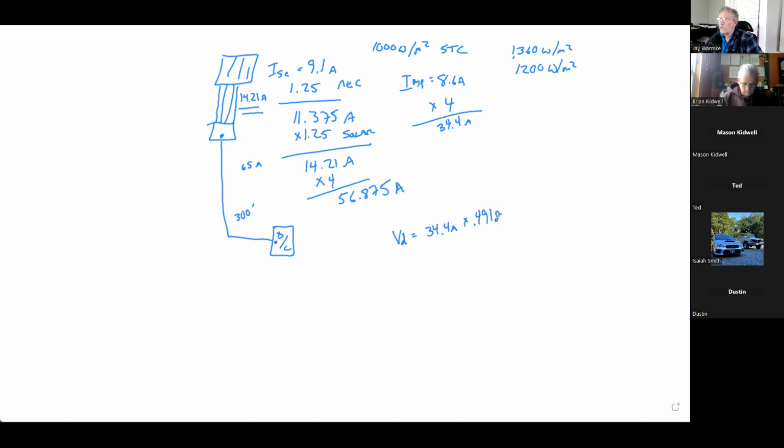0.491 ohms times, well, I said it's 300 feet. 300 feet times 2 divided by 1,000 is going to give me 0.6, right? 600 feet divided by 1,000. So then I take the numbers here, 34.4 times 0.491 times 0.6. So I'm now going to lose 10.13 volts.